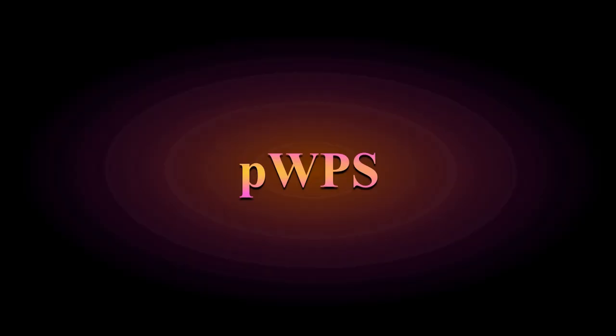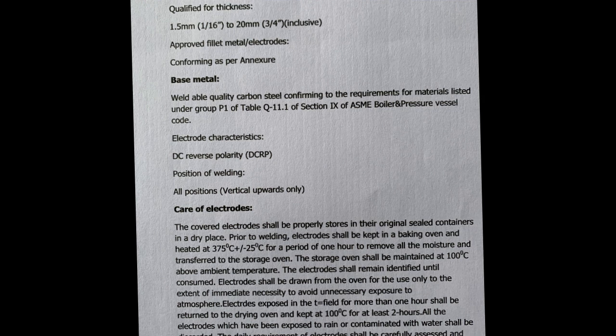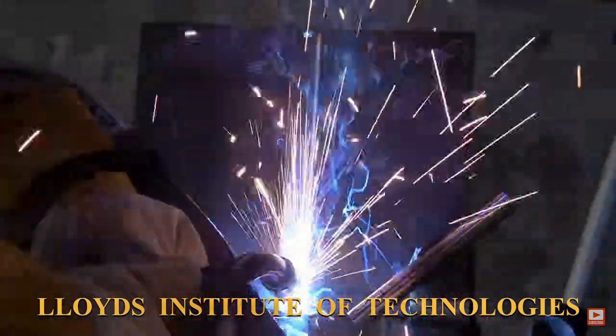Before we prepare a preliminary WPS or draft welding procedure, we should recall the important necessary points like project specifications, necessary standards, parent material specification, welding process, joint design, accessibility, position, and so on.